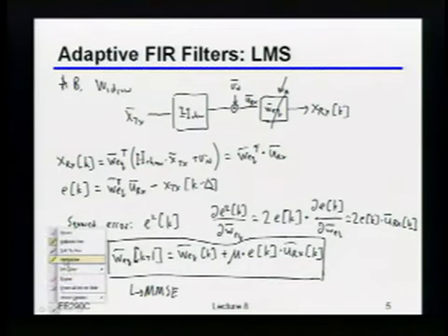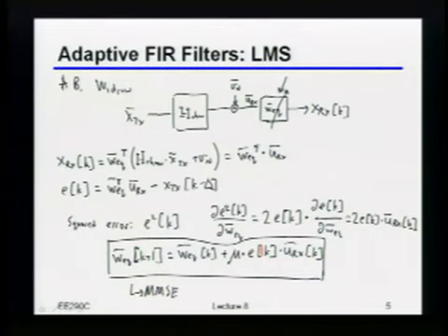What you're really doing is taking the error that you saw on this individual sample, but correlating it not just with the input to the equalizer at that particular sample, but also with previous inputs into the equalizer. Because since you're trying to create a filter, you need some information about what errors were being created by the channel over time. So this E of k, even though it's the instantaneous value, I want to know how much of this error came from the previous bit, how much came from the bit before it, and how much maybe even came from the bit that will follow, due to precursor.